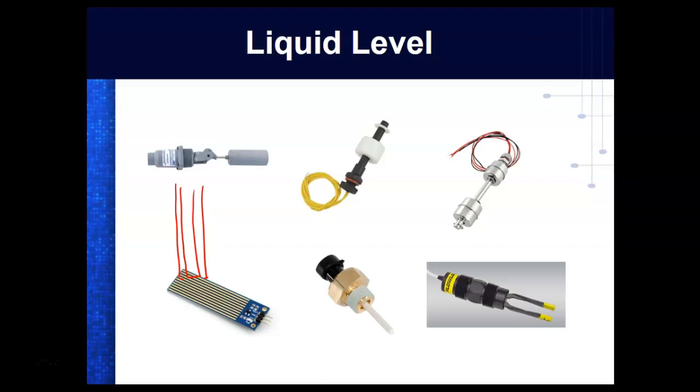So we had what we call a wet wing tank. The planes I worked on had wet wings. I think they could put about 2,000 gallons in each wing, and then it had a belly tank that was 5,000 gallons. So it could hold around 9,000 gallons of JP fuel, jet fuel, which is kind of like kerosene, by the way. It's a little different. And that was one of the systems that we had to work on, by the way, the fuel system.